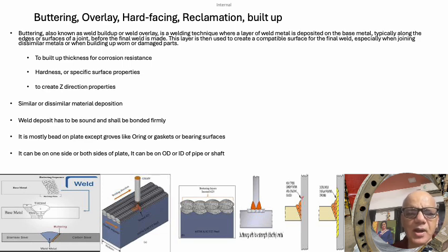And when we are welding and doing buttering, at that time there is no stress because it's kind of a buttered plate, so you don't land up into it. Now what we are going to see in the next slides is, like any other welding, what are all the care and precautions we need to take while depositing either the complete buttering on one side, on one of the plates, which is maybe a mild steel plate, and the other side is stainless steel, and you want to join it, so you butter it with 309 stainless steel grade and then weld it together with 308.